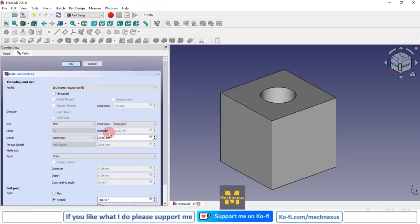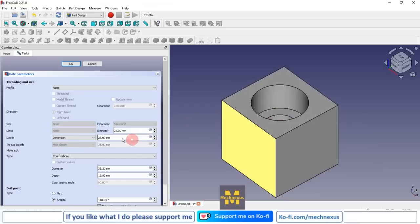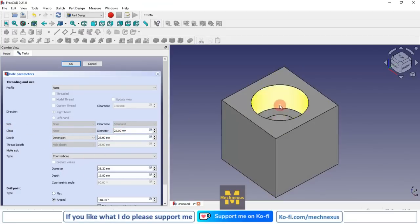Now let's try the counterbore holes in FreeCAD, and how we can give the counterbore holes. So here in the profile section, click on none, so that the threaded hole option will be turned off. Now from the hole cut section, select counterbore. So you can see that a counterbore is created where the diameter is 22, depth is 25. So this bigger diameter is 35.